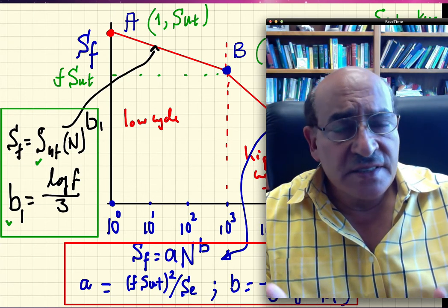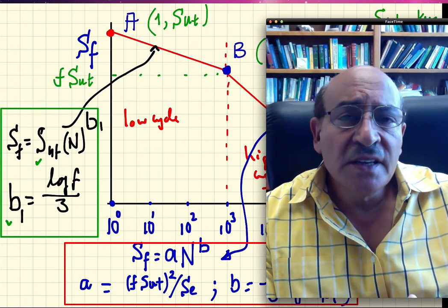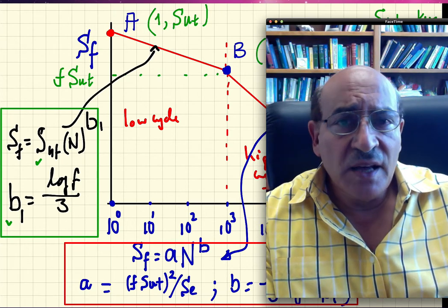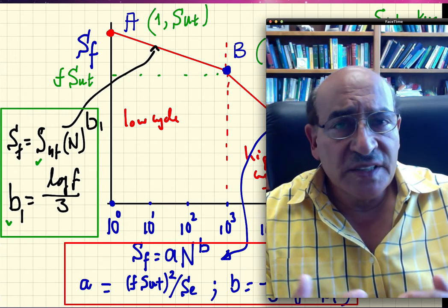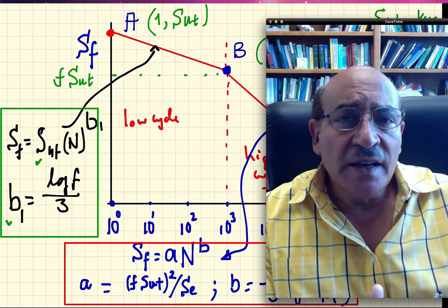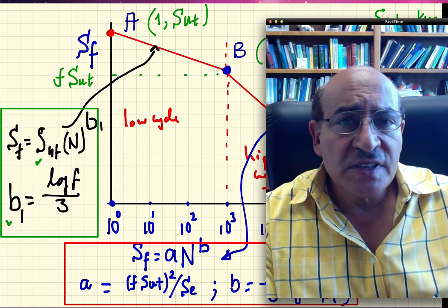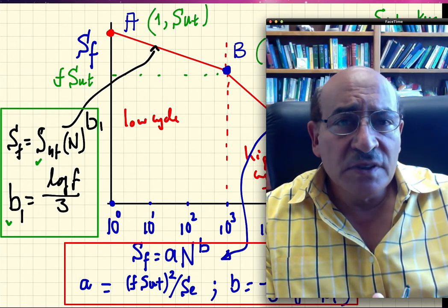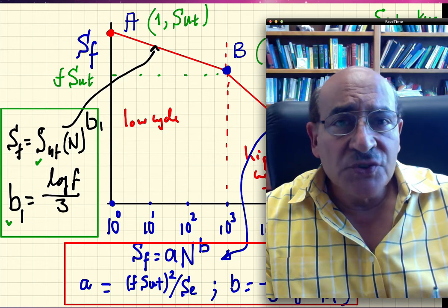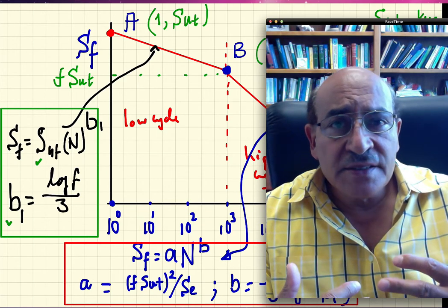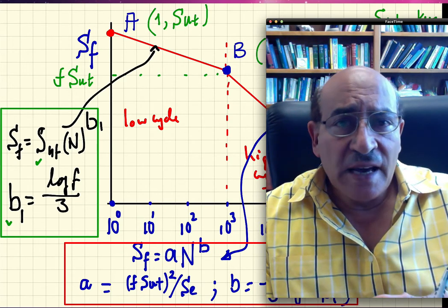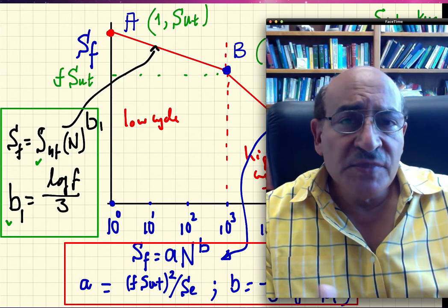what you see is not what you get, because the endurance limit is based on a rotating beam specimen that is highly polished and under very nice control. But in real life, the surface conditions will be different, the size will be different, the environment will be different, the temperature and so forth. So there are a number of design factors that need to be accounted for to give us an extrapolation of the fatigue data that we obtain in the laboratory to the fatigue data that can be used in real practice.